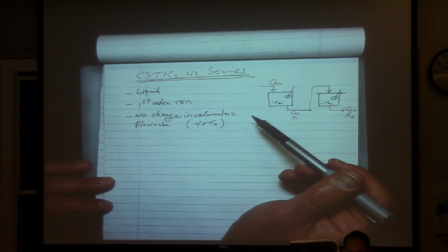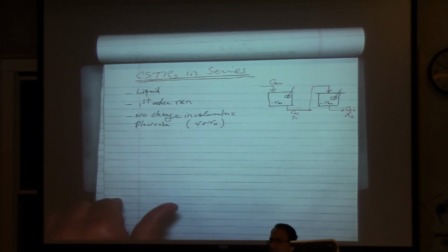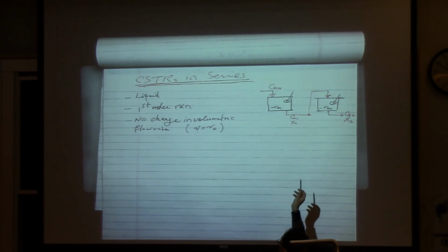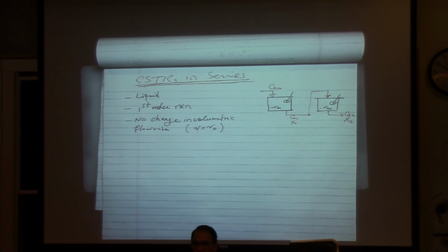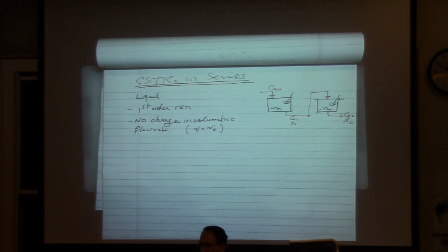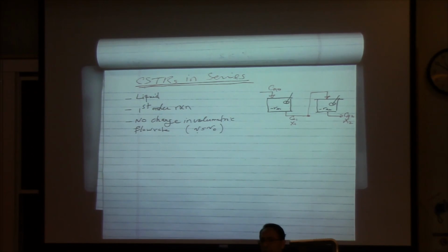Again, in the context of your course, we only consider pressure drop for the packed reactor. We just don't consider the pressure drop here, between the two reactors. In reality, you're going to have maybe a half meter pipe, and that's not going to have a significant pressure drop. Pressure drop, remember from fluid mechanics, is when you have long piping, or a lot of bends and fittings. So we don't consider the pressure drop here. The pressure drop that we consider, and I will discuss this in 2 lectures, would be when you are dealing with the packed reactor. You have the catalyst in your reactor, and then the flow goes through the catalyst and the pressure drops.